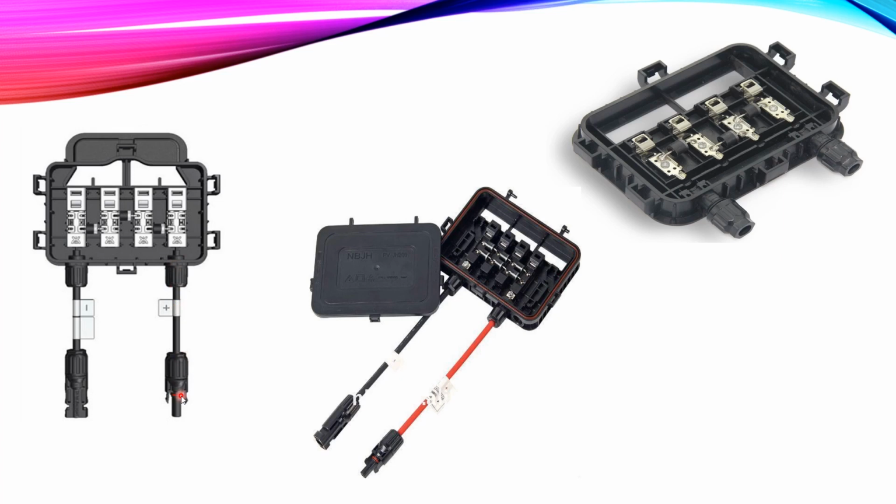Now we have the positive and we have the negative. In order to connect them in series, we connect the positive of one panel with the negative of another panel, and the positive of that panel is connected to the negative of the next, and so on, as we discussed in the series and parallel connection of the panels. And if they are in parallel, then the positive is connected with the positive and the negative with the negative.